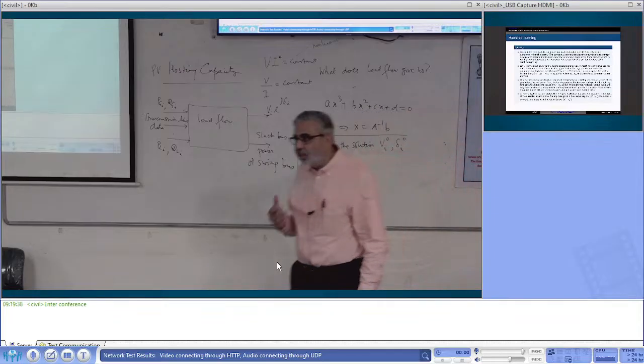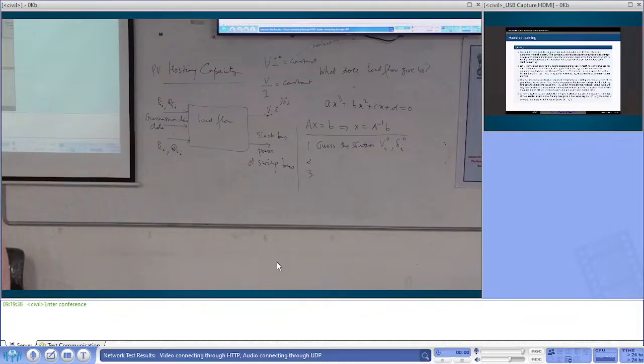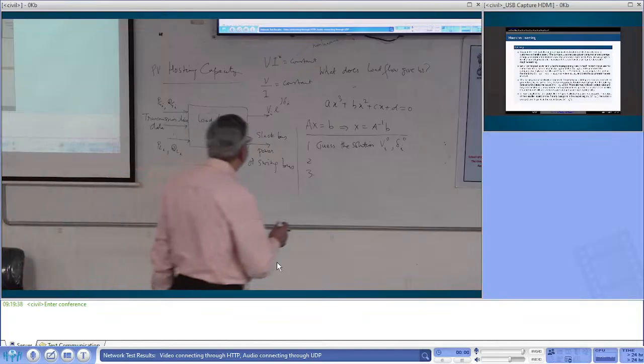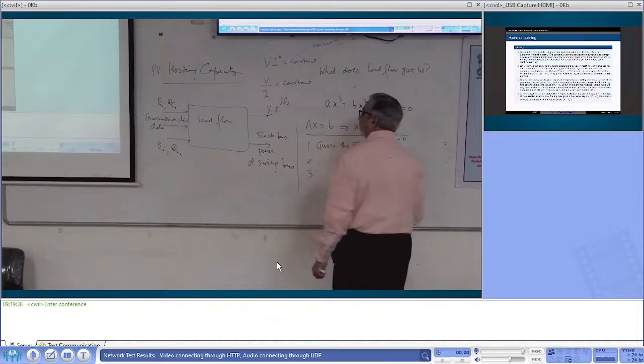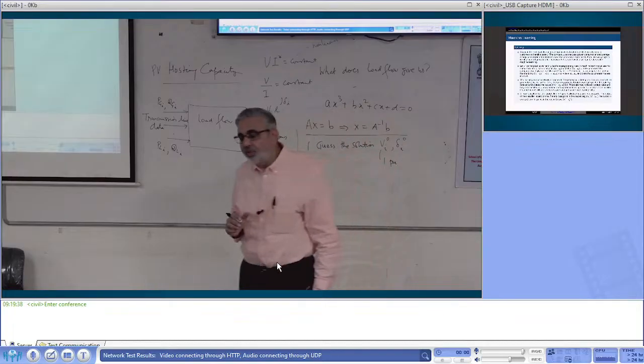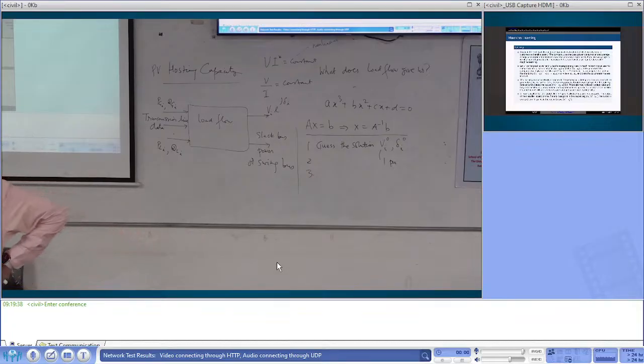Now this is where some of the insights of power system engineers come in. Voltage, you can guess anything. What is our normal guess? 1 per unit voltage. It is such a wonderful setup of power systems that 1 per unit is the base voltage and all that.